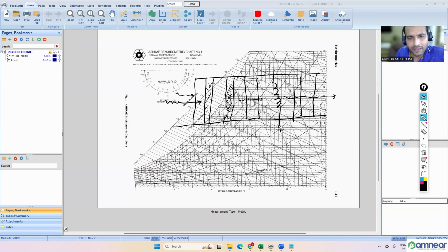In normal cases, the desiccant wheel removes the necessary moisture, and then the cooling coil cools the air until the room condition, and then we can deliver it. But in a hybrid system, the wheel can also come after the cooling coil. Anyhow, we can discuss that.